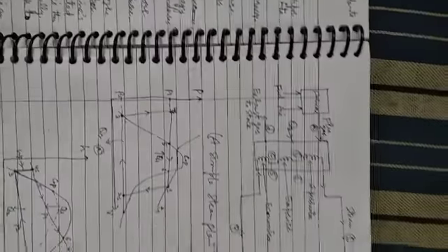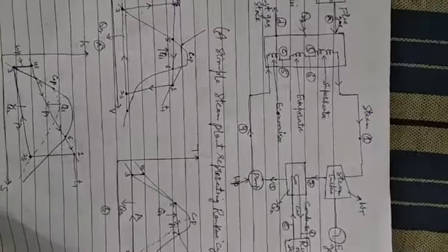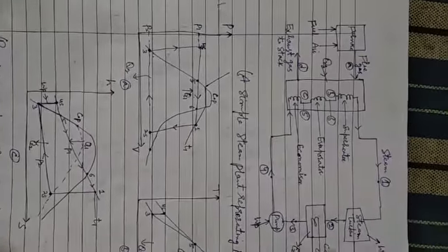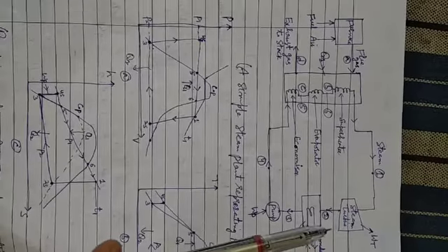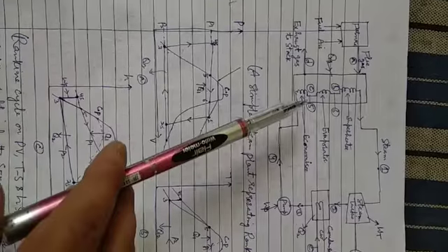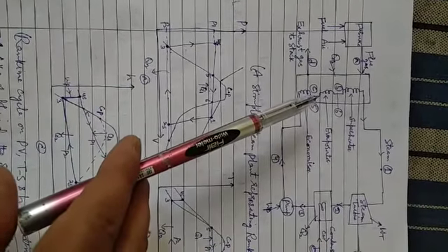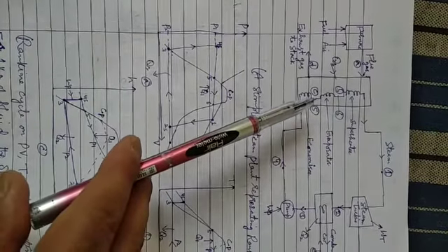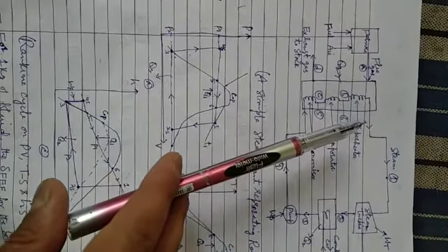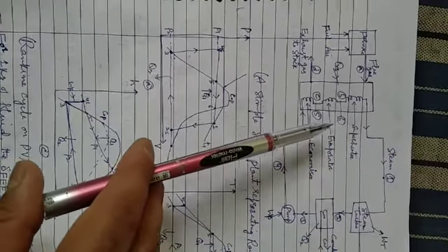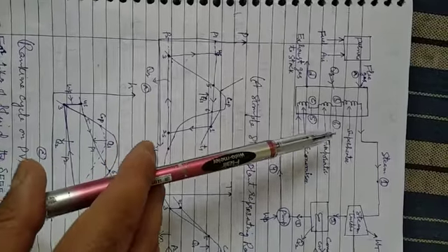If we go through its systematic view, in the Rankine cycle you can see there is a steam turbine, a condenser, a pump, and a boiler. In the boiler, the water has to pass through three stages before it finally forms steam. Those are the economizer, evaporator, and superheater. So the boiler consists of three parts: economizer, evaporator, and superheater.